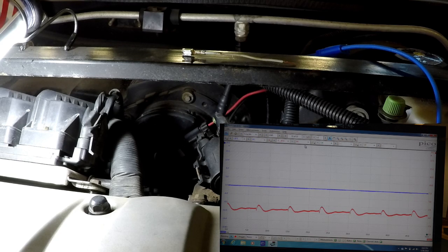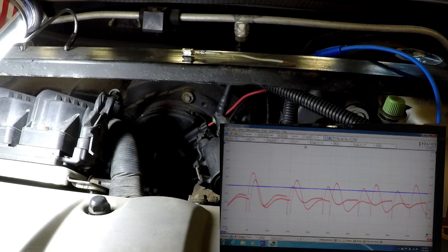So the reason I went to this length to diagnose it is because the retail for at least the OE part, the Delco part, is somewhere in the neighborhood of $450 for that. So I wanted to check to make sure that absolutely there was no doubt that the blower motor is at fault here. And there it is. So I'll go ahead and replace the blower motor once I get the part, and that'll fix the situation. We'll no longer have any kind of battery drain with the blower motor plugged in.